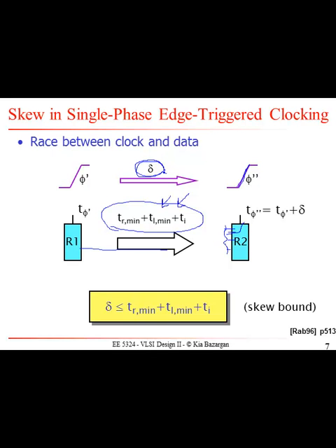I mean, basically, if you look at this delta, the amount of skew that you could have on a clock could be potentially large because the clock tree that is delivering the values to this R1 could have a bunch of branches going out. So the capacitive load on this, remember Elmore delay? So the capacitance value on this downstream tree could be pretty high, which makes this value significant.